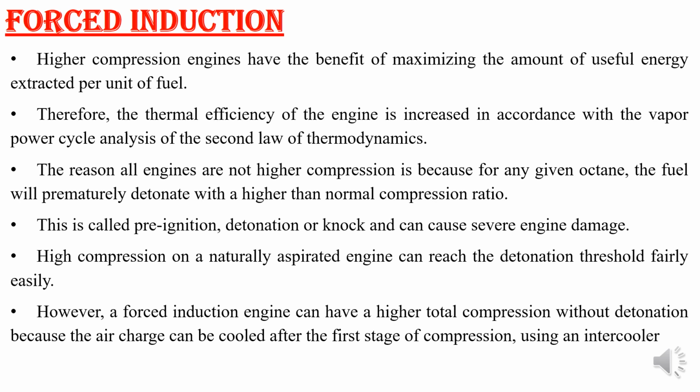That is one major issue we have to take care of while introducing a supercharger or turbocharger into your system. High combustion temperature as well as high oxygen content in your combustion chamber will lead to high formation of NOx emission, and so that part has to be taken care of very effectively. Okay, so this is about your post induction system.